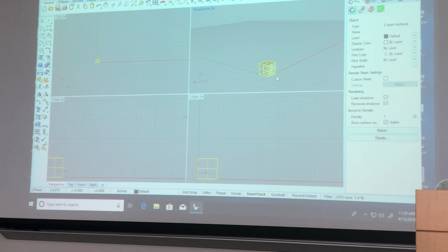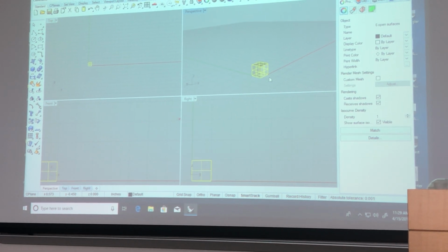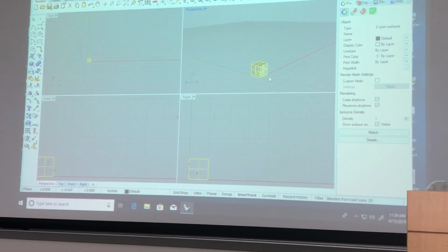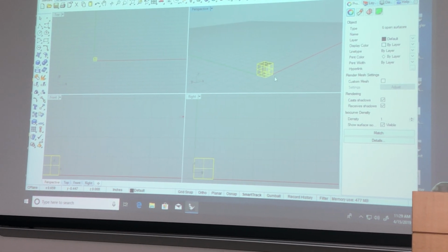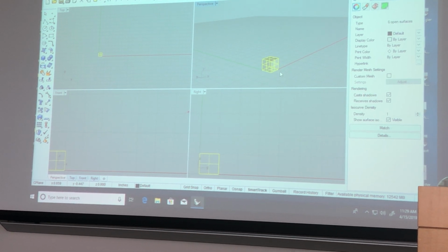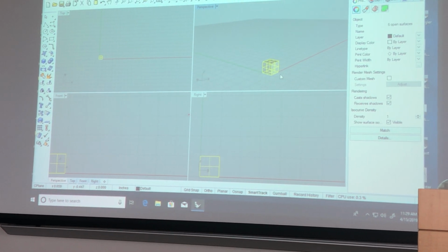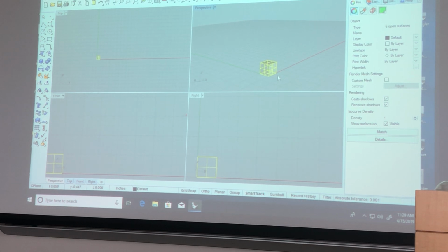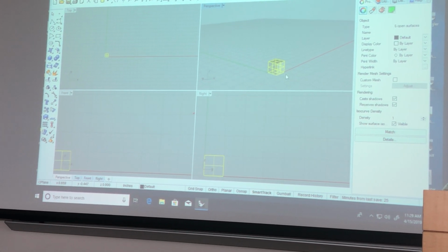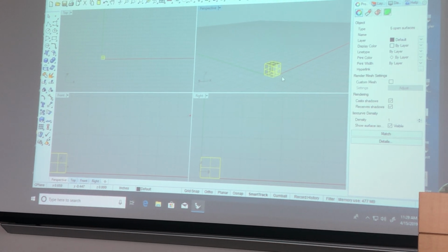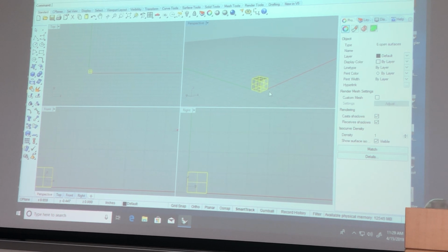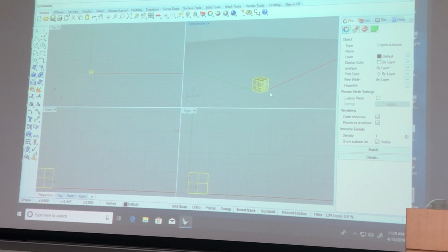If your Rhino file is really messy, if you model really sloppily, if your things are two-dimensional and weird, it can take a long time to figure out what's wrong and fix it. If you directly import your SketchUp model and attempt to print it, I will refuse to service you. The average SketchUp model takes me 6 to 8 hours to fix.